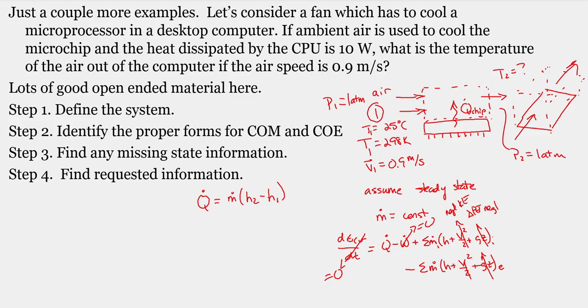Okay, but that's not the temperature. We're looking for temperature. I used the conservation of mass. I used the conservation of energy. Those are my two big guns. Those are my best tools. What's left? I need another equation to connect enthalpy to temperature. And at this point, you should all be having the aha moment that it's air.